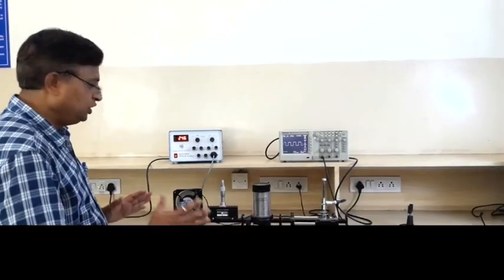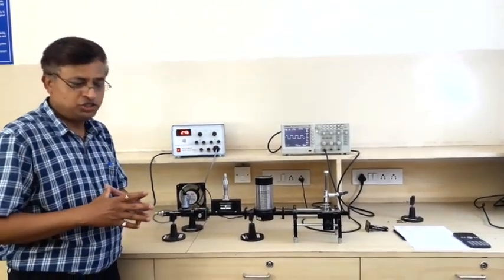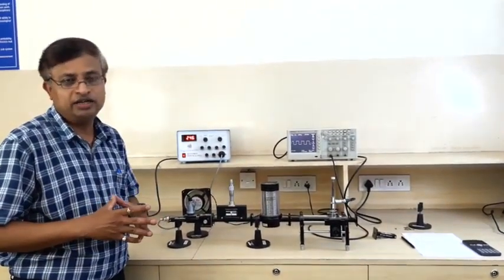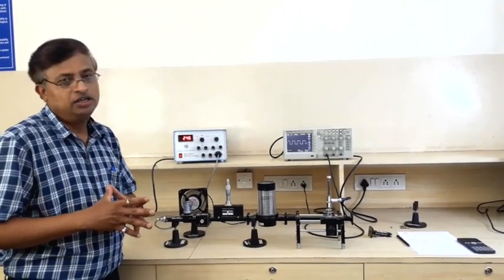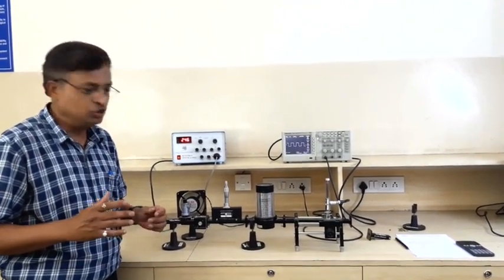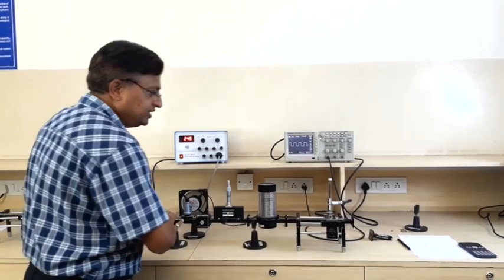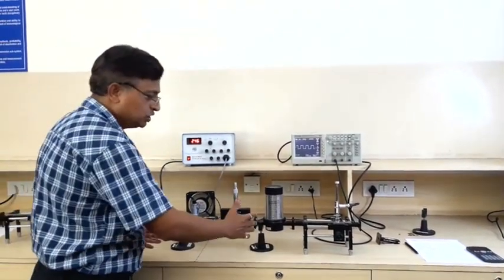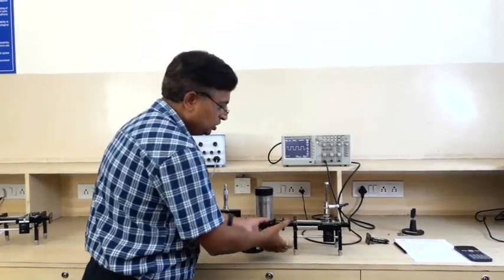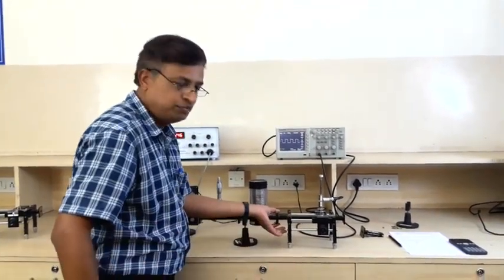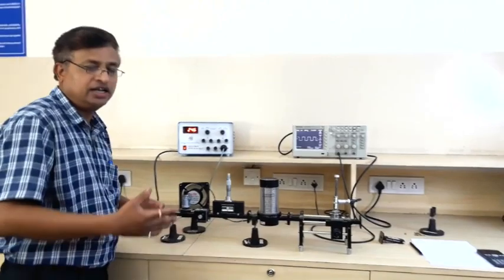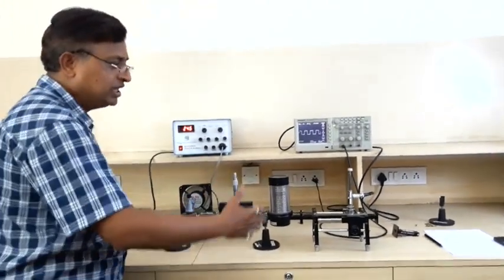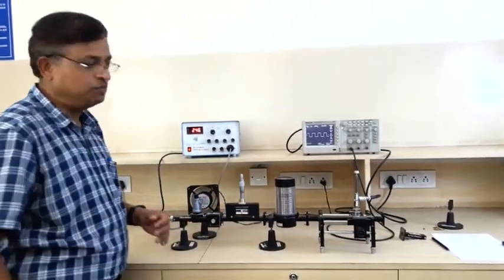Now let us use the same microwave bench which is operating at X band frequency, which is in the range of 8 GHz to 12 GHz. So again, the similar setup of X band source can be used to give the signal to the slotted line section as an input, and using the slotted line Vmax and Vmin, we can calculate the VSWR.